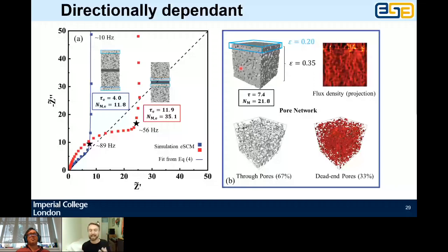Okay, and this is exactly in line with our expectations. This is a real effect that you see in real electrode manufacturing processes, where you can have, for example, non-ideal drying rates from your electrode, and you can end up with a skin, almost like custard skin, settling on top of your electrode and forming a low porosity layer on the top that doesn't allow trivial transport of your lithium ions through the pore network. So this is really important to be able to differentiate this.